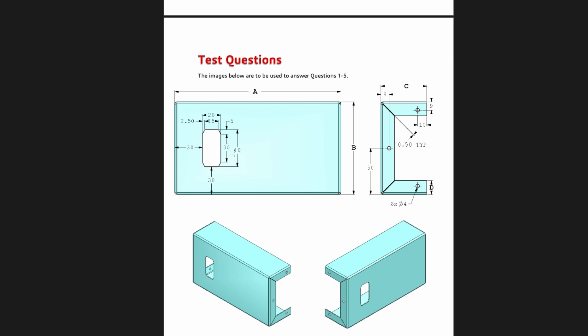Let's look at the dimensions here. 40 tall, 30 in that little part, a couple of triangles. And I'm seeing a redundant dimension here. This is going to be over-defining if we put that 2.5, but it's whatever. So 30 from an edge, 30 from that outside edge, and we'll go ahead and do that.